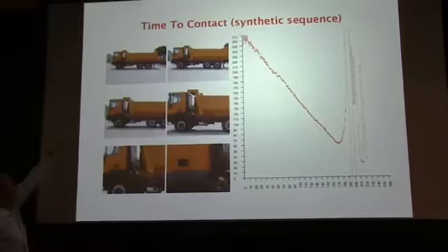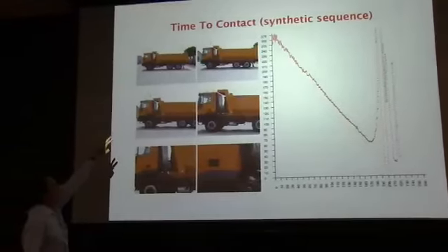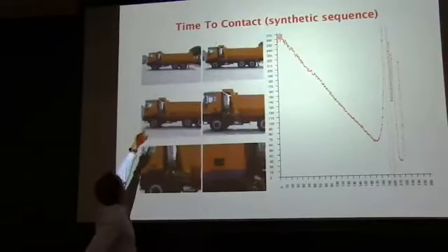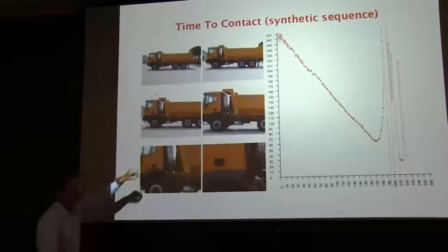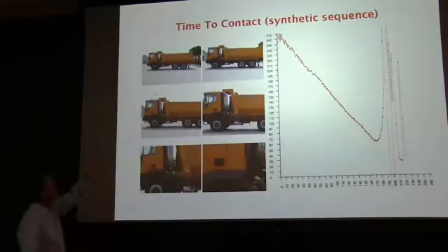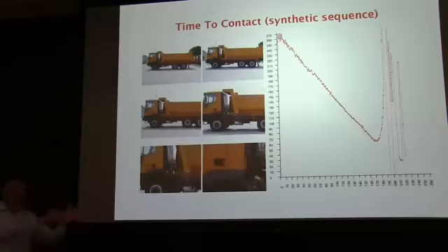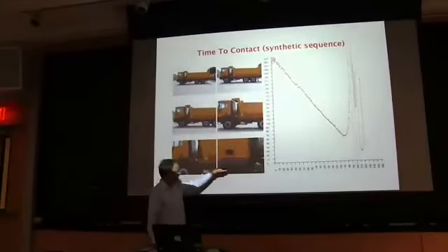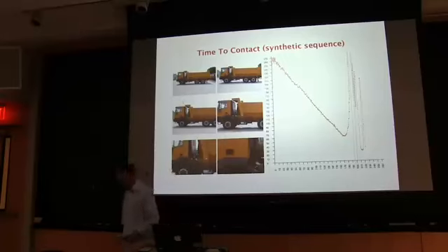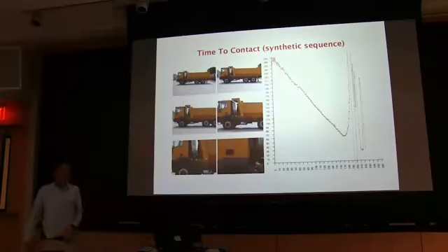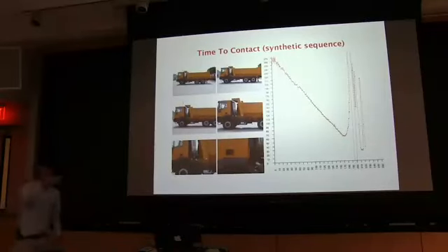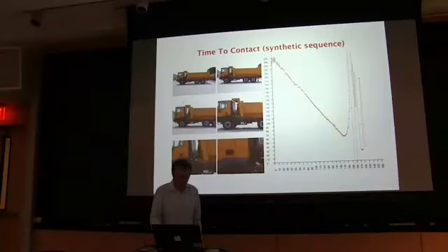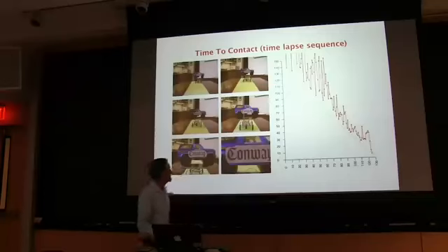As we approach this truck, you'll notice that we end up on the door, which is not the center of the first image. So we're actually moving at an angle. We're not moving straight along the optical axis of the camera. The focus of expansion is very important because it tells us in 3D what the motion vector is. So in addition to finding the time to contact, we want to find the focus of expansion.